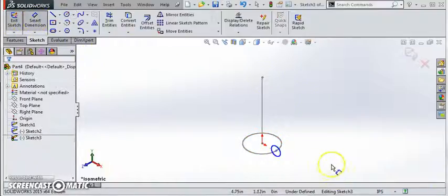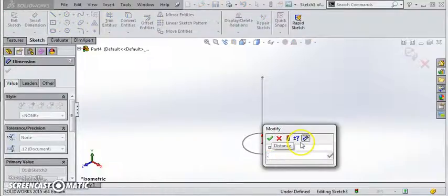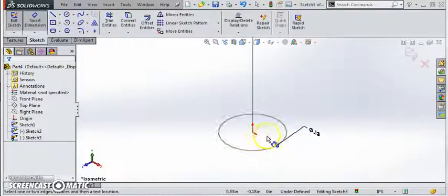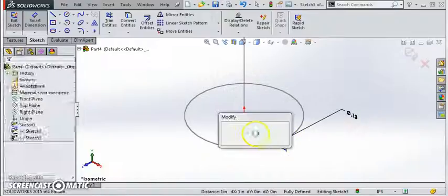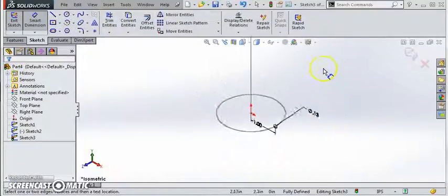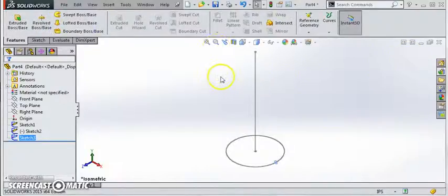We'll make this a 1/8 inch coil diameter, so let's dimension that. And also want to make sure that we define this as being exactly 1 inch, or half the diameter of our base circle that we created. We have our sketch there.